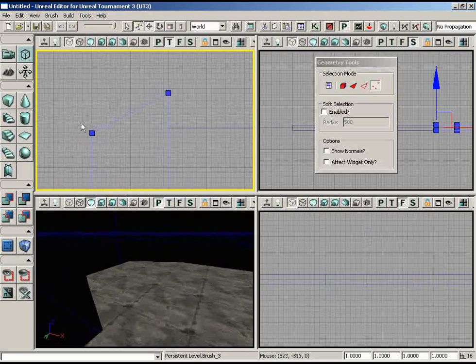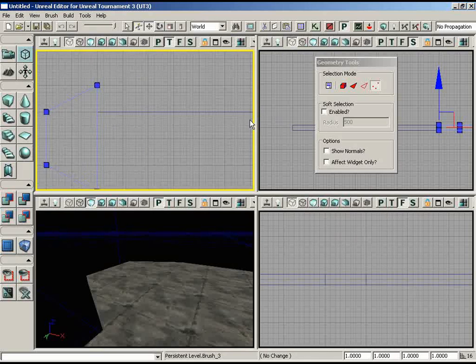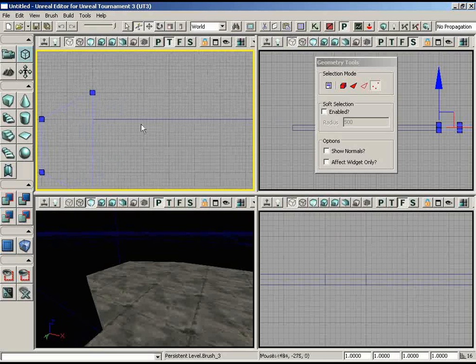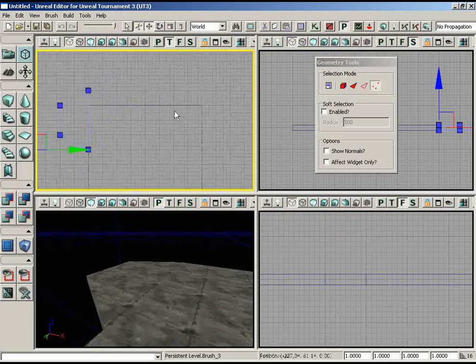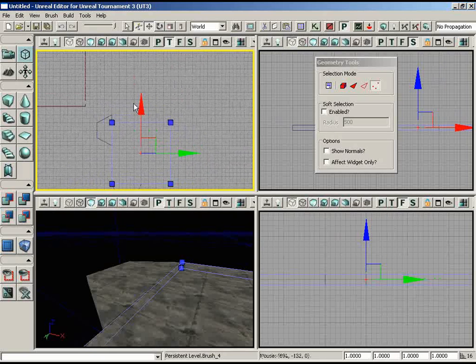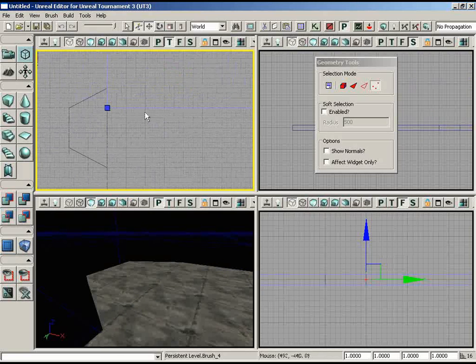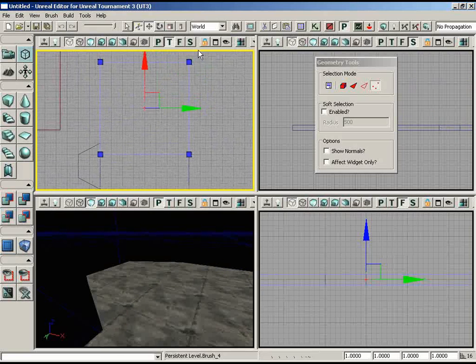so that this vertex, or these two vertices, will line up with the edge of the main room brush. So that means I need to drag it just a little bit more, and we have it lining up there. So now I can see the area that I need to fill in with the final brush. And for that one, let me grab the main floor once again, Alt-drag to duplicate it off, and align it up on the X edge, so that's all aligned.